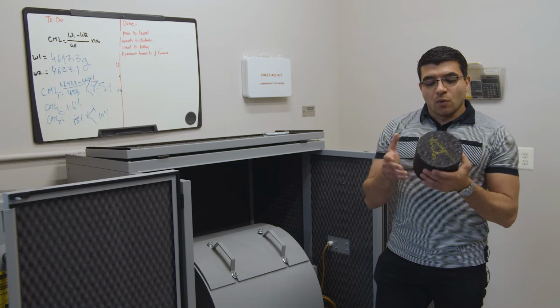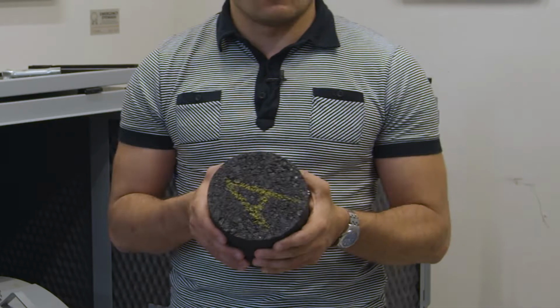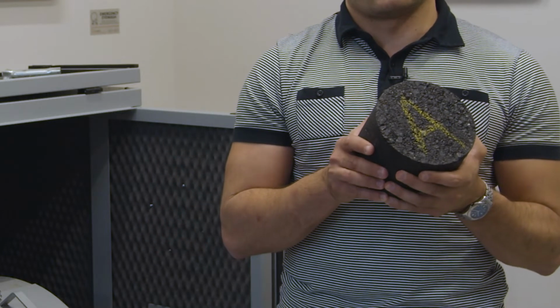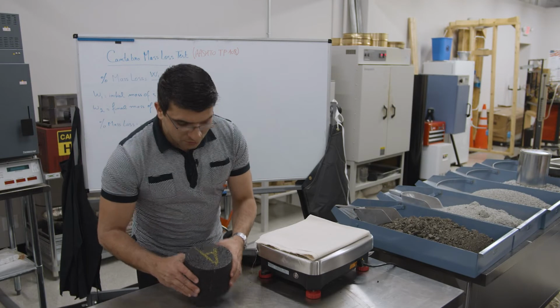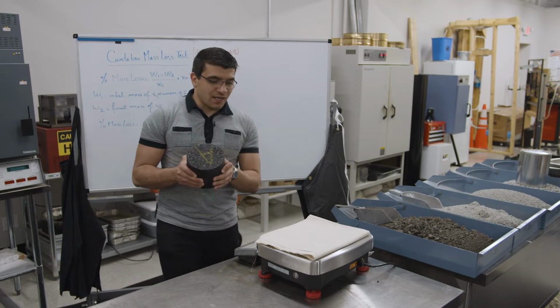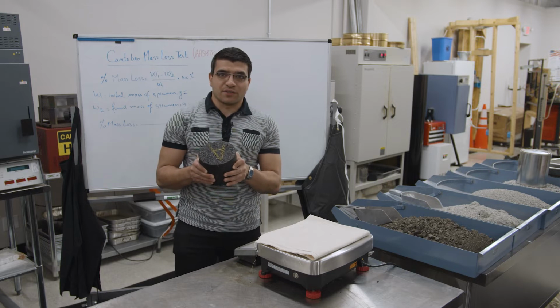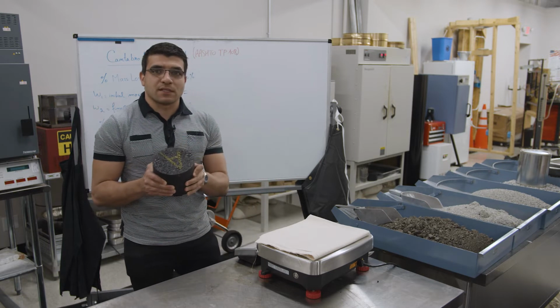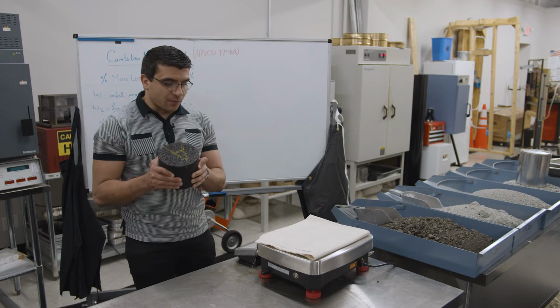First of all, once the specimen is dry and brought to a temperature of 77 degrees Fahrenheit, we're going to measure the initial weight of the specimen prior to conducting the test. So after making sure that our specimens are dry and left at a temperature of 77 degrees Fahrenheit or 25 degrees C, the first step consists of determining the initial mass of the specimen prior to performing the test.